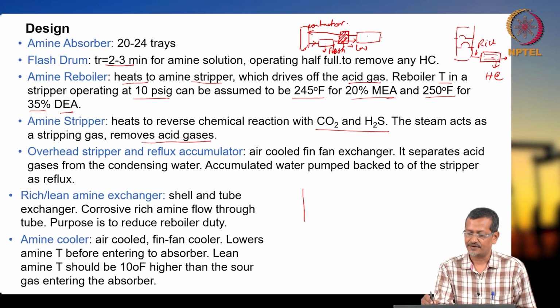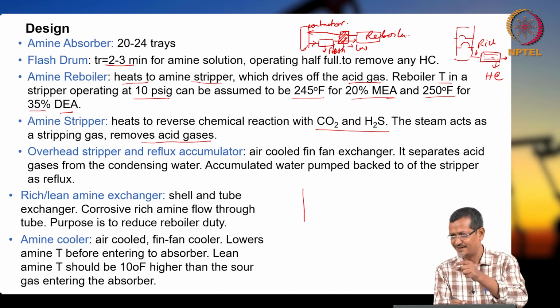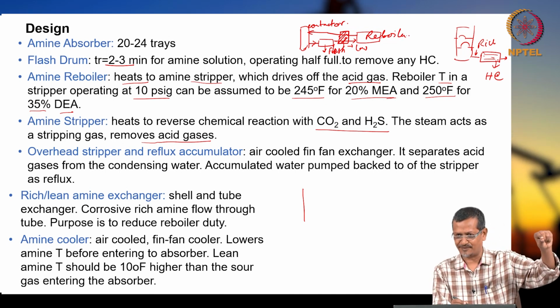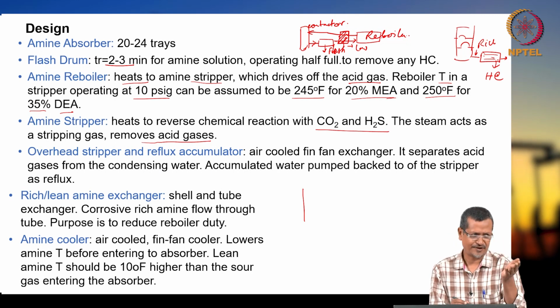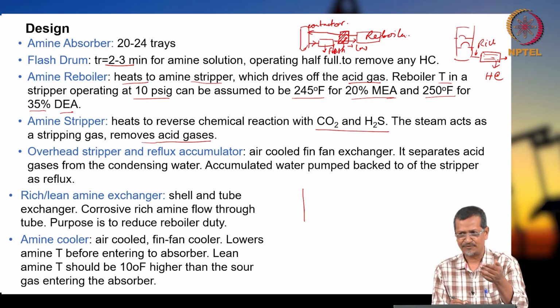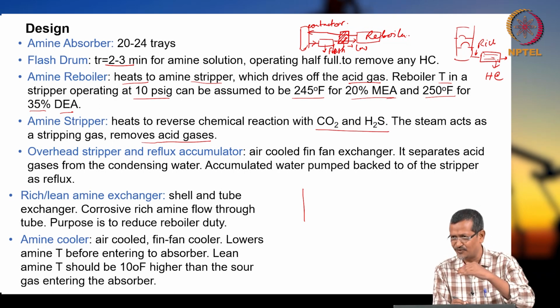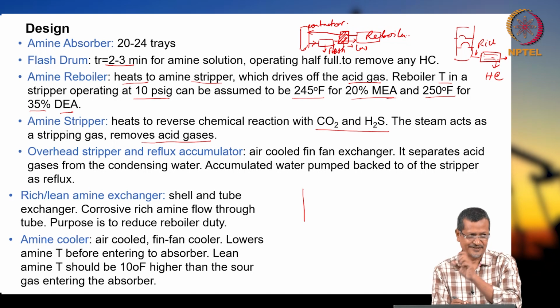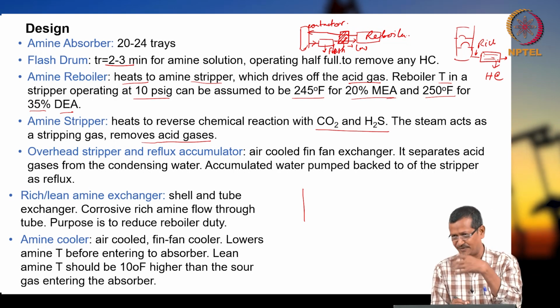If after the reboiler the temperature is very high, you cannot put that into your contactor column. You could waste that heat with a condenser, or you can use that heat to increase the temperature of the inlet fluid of the reboiler. So you can reuse the heat and increase system efficiency.